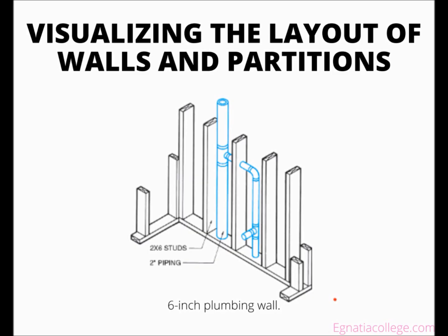Some plans list overall dimensions for each room. The plans for the lake house give this information by conventional dimension lines only. Many of the dimensions of the lake house framing are referenced to the columns of the structural steel core. The faces of some of the walls are an inch or 2 from the center lines of the columns, but for the sake of visualizing the layout of the house, these centerline dimensions are close enough to develop a good mental picture of the layout.